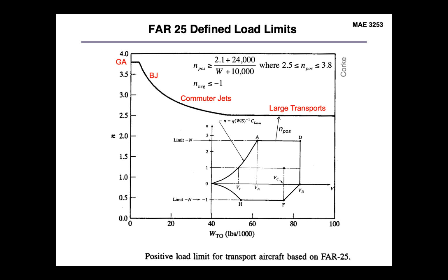So that's still pretty stringent in terms of designing the structure of your aircraft. And this again has to be that minimum value. You're typically going to design over this as well, with a margin, say, of 25%, in order to be able to make sure the aircraft is not damaged as you're flying up to this limit.